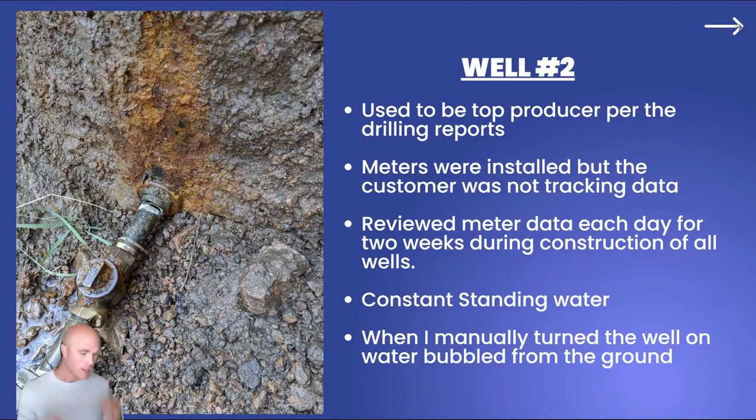It taught me that the raw water lines can have higher priority than the main lines. They can also have leaks. So you don't only want to just focus on, okay, treatment plant sends out this much water, that's my water pumped, and then I sell this much. You could be just paying to pump water into the ground like that, like well number 2. So just something to keep in mind as we move forward into the later part of this presentation.